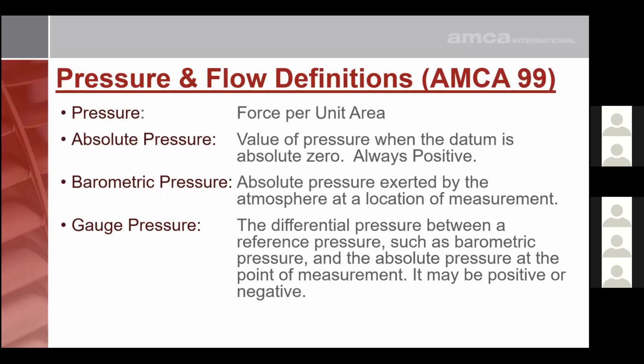So looking at AMCA 99, we've got some basic definitions. I'll go over this quickly because you will get the PDF. You can go over this in more detail yourself later, but pressure is essentially a force per unit area, whether it's PSI, or in fans, we typically look at inches water gauge or inches water column, and in other parts of the world, they'll look at pascals or kilopascals.